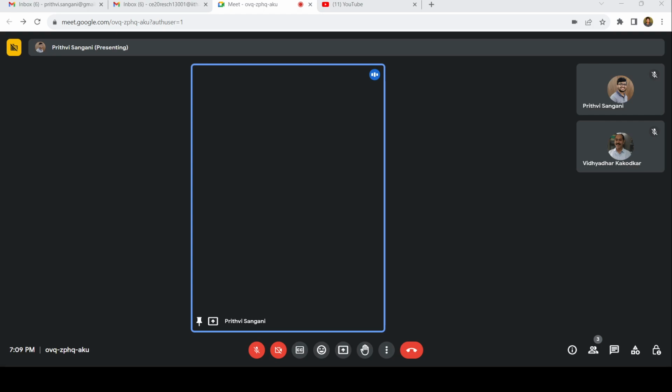So for the other part we need to apply the virtual force, the virtual load, right? So the virtual unit load. Usually we call it unit load directly. So let me apply a unit load of 1 kilonewton. When I am applying 1 kilonewton load over here, right?